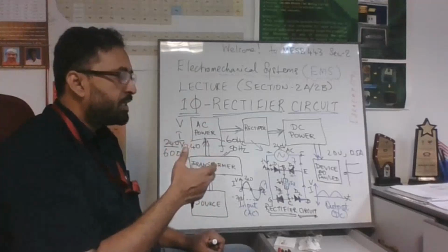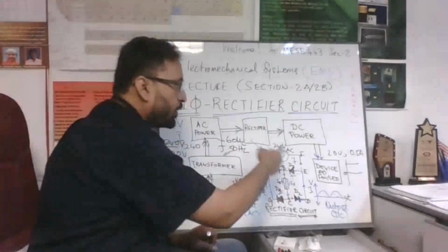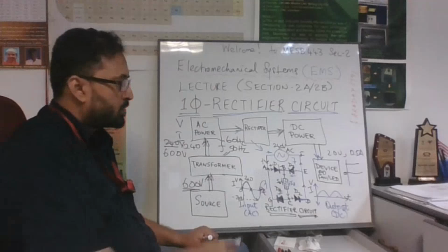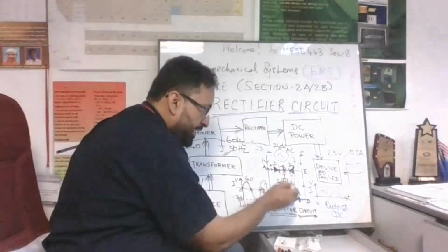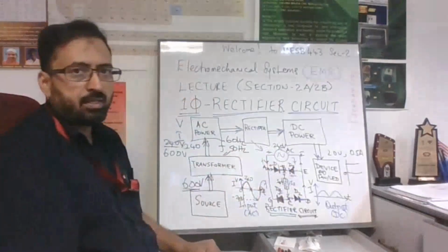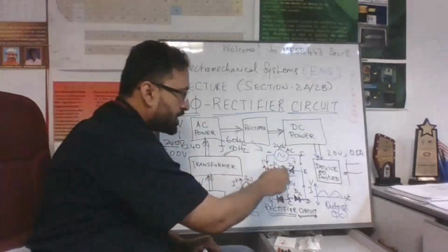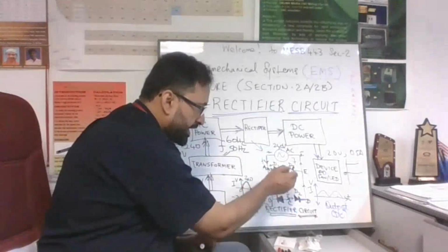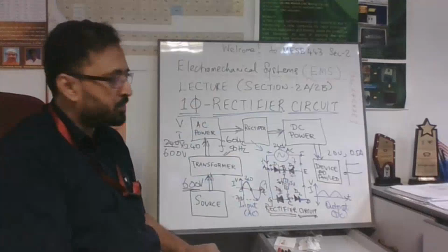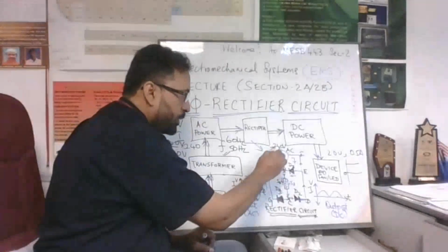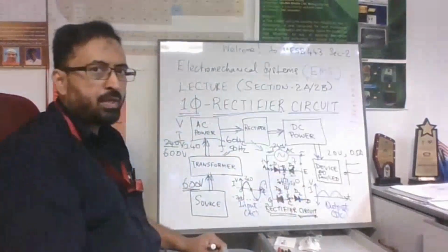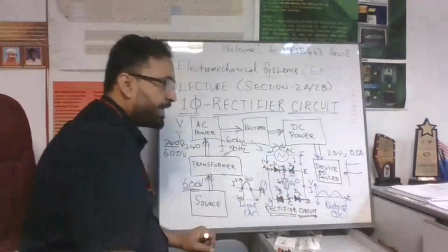So we are utilizing the diode function to perform the circuit operation to convert the alternating current to a direct current. Here, between points B and C, we actually get a direct current. Whatever the cycle of the alternating current, positive or negative, the current flowing through the resistor between B and C is going to be in only one direction. Therefore, it is considered direct current. So this is the alternating current input, and the output is here. Between B and C, you get the output voltage, which is in direct current form.